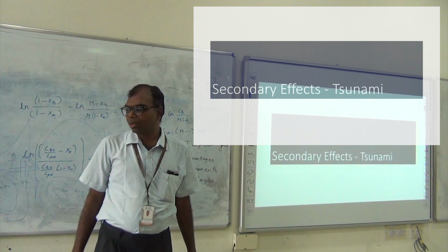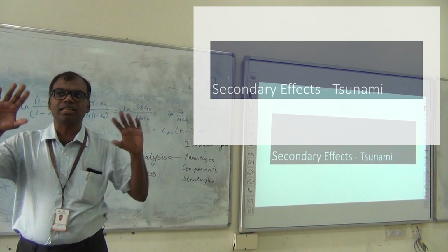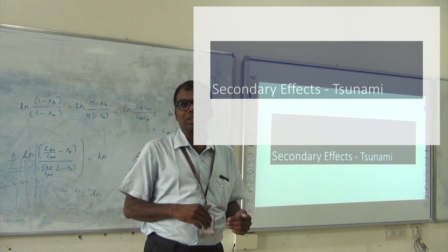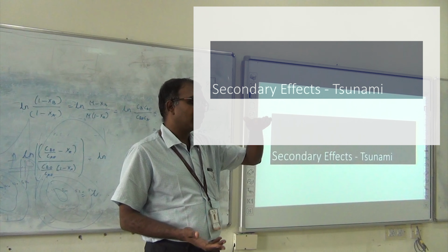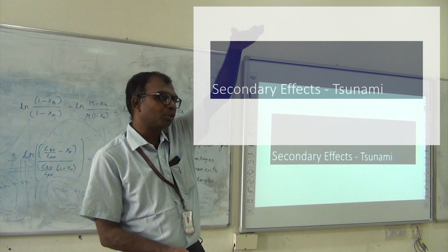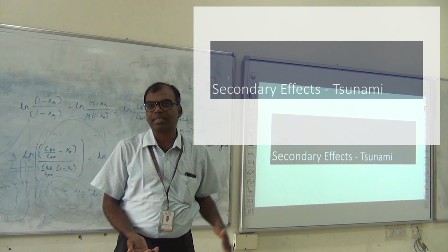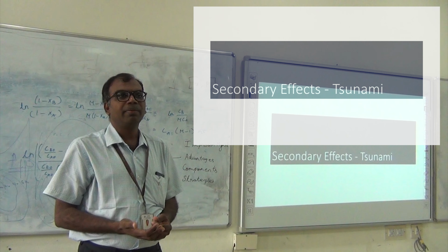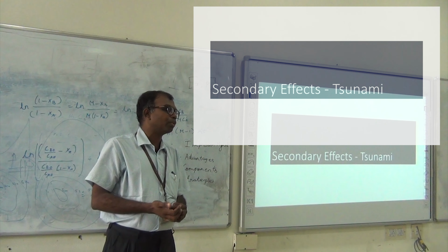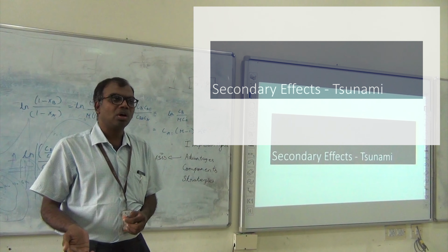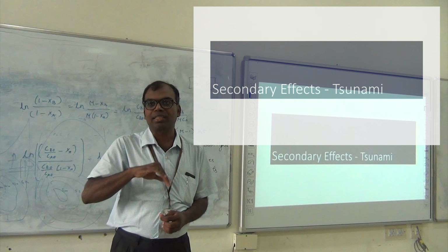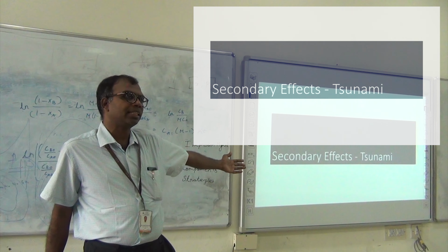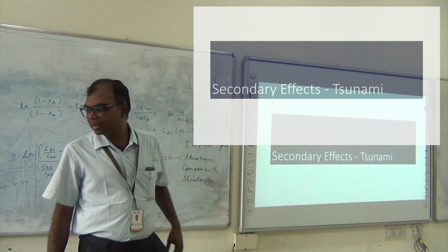Okay. Now till now what we have seen is an end-to-end package of what happens due to earthquakes. Earthquakes can strike the building. It transmits the forces to the structure by way of a base excitation. The entire structure responds to the earthquake. We can make the structure strong enough to take up the forces, or we can give it a way by which it doesn't respond to the earthquake. And for that we've seen two things: the base isolation, and the tuned mass damper.